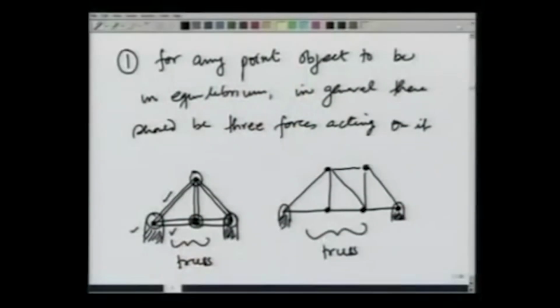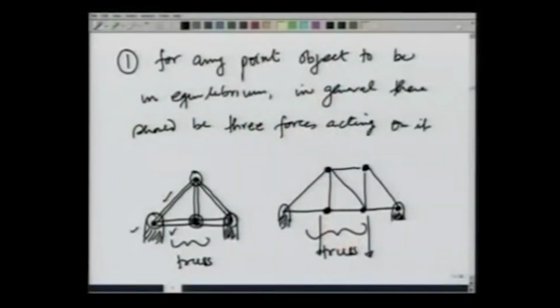So, you see, if I keep making structures like these, I would provide at each point enough forces to keep that point in equilibrium. If I load this structure somewhere, I could load it with some weight here, I could load it here. Each point can be brought into equilibrium by forces generated in these members. These members would provide just the sufficient forces to bring this entire structure into equilibrium, and in the process transfer this load onto the fixed supports. This is the job of a truss.